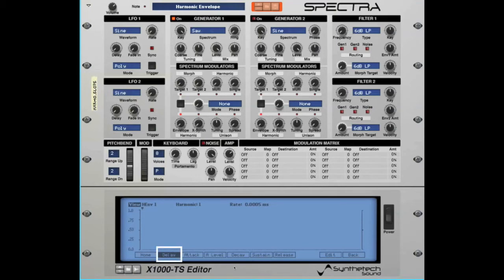In this instance, Harmonic Envelope 1's delay stage is being viewed with Harmonic 1 currently selected. The magnitude or level of the selected stage element is also displayed in the caption. The navigation bar at the bottom of the screen enables you to navigate to each stage of the harmonic envelope. The main display area depicts the rate or level for each of the 256 elements of the currently selected stage.